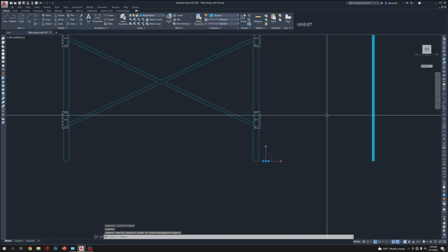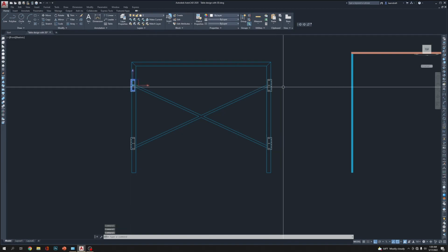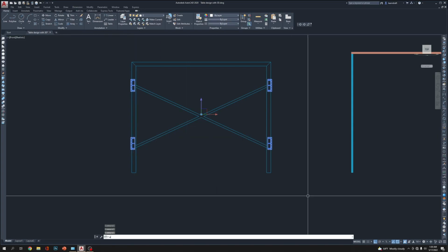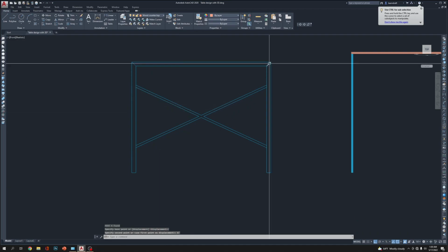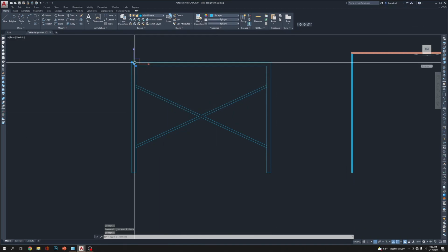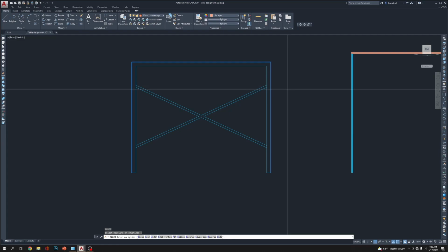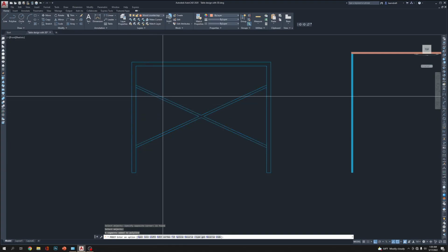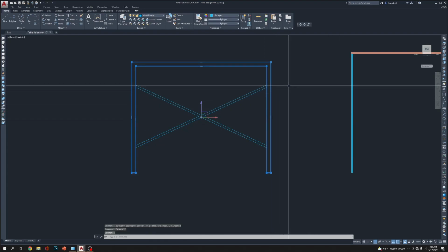everything. Hinges is a block, keep it there, but let's move it. Move it like 6 feet. Take out this corner, take out this corner, poly edit, select this, join. I'm windowing selecting everything. It's going to deselect these and make that one. Extrude. Oh no, let's